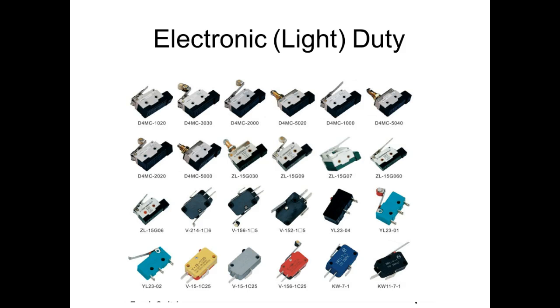Any questions? The light duty is not designed to run a load. Heavy loads. We can't say, because it's a switch. Somebody out there is going to run something off of it, right? You understand? They're not designed to run a heavy load. They can run light loads, but not heavy loads. So technically, the input of a PLC is a load. But it's only like, I think 40 milliamps is what most PLCs pull. So that's not much at all, right?